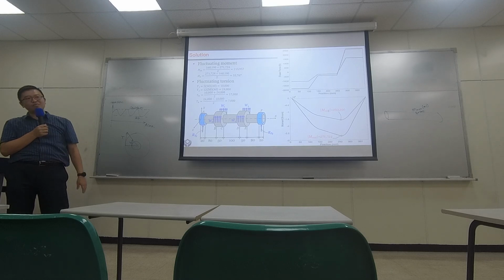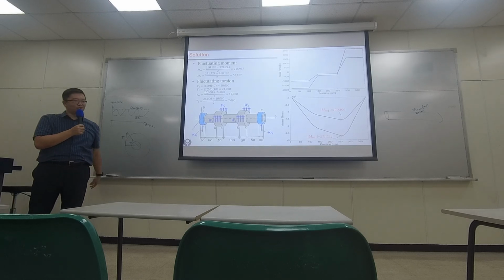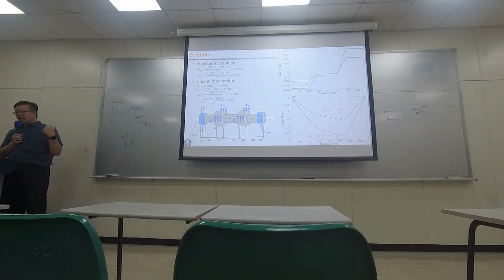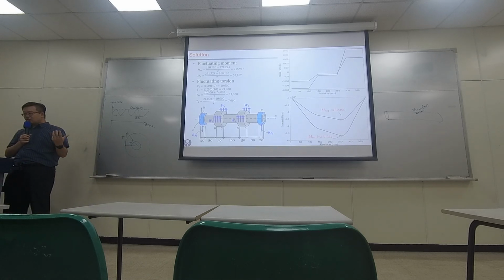That's why in exam 1, I said just ignore torque. Okay, so if you can do this, you realize the shaft is actually not rotating. However, due to the fluctuating belt tension, the moment inside the shaft and the torque inside the shaft could be varying with time.